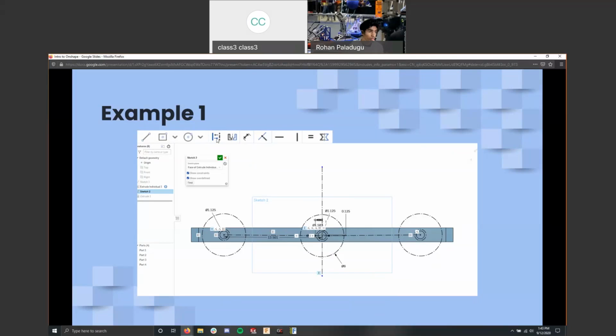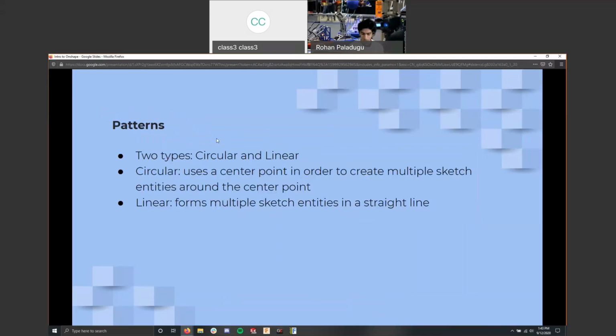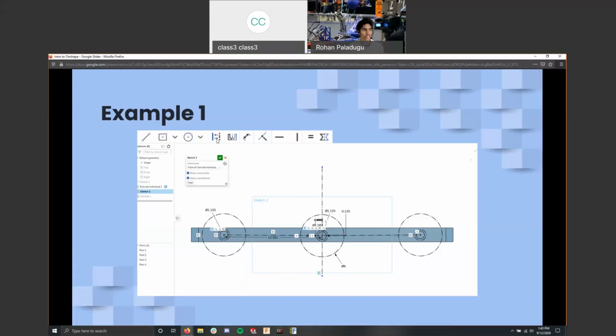And what we have here is this little funky symbol. It looks like it's turning a regular solid line to a dotted line and back. So what does that look like? Well, that's construction lines. What those are used for is whenever you go to exit a sketch and you want to create a 3D object from that sketch.